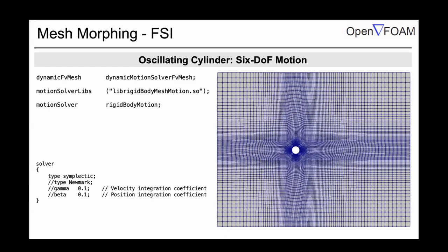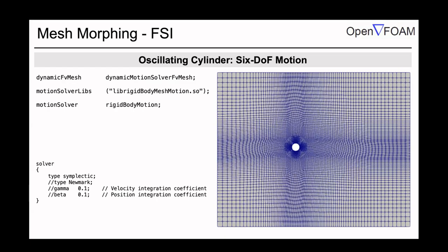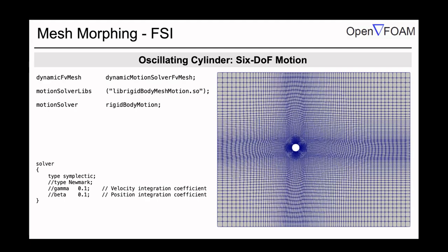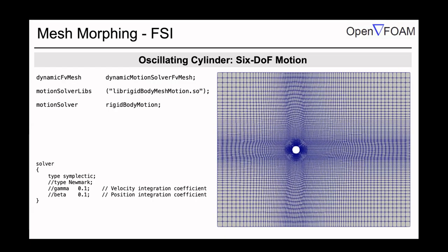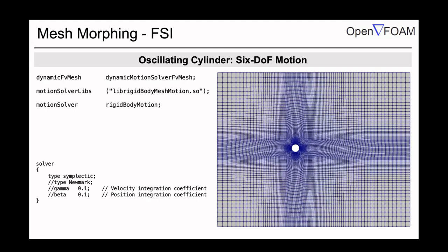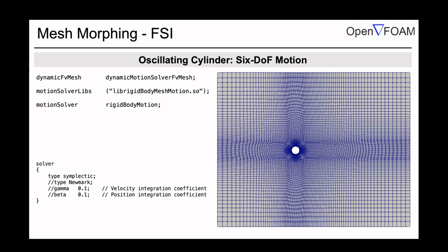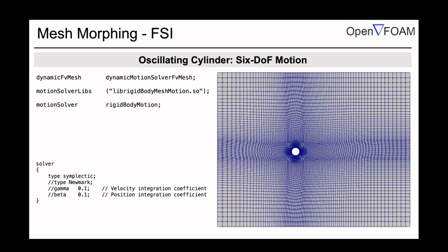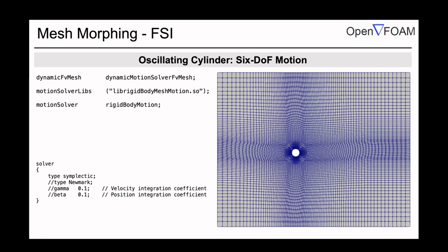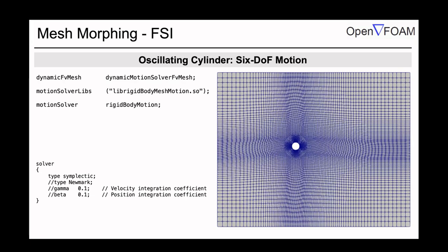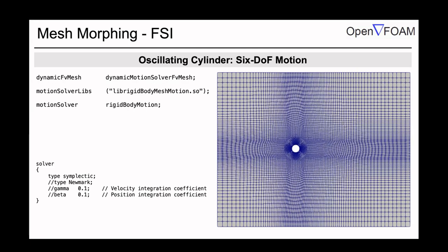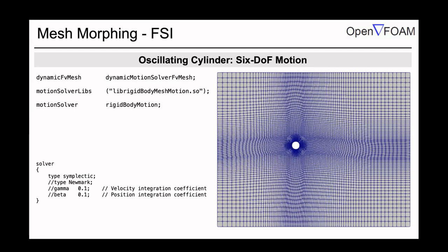And apart from all the structural parameters, you have to use a structural solver, which will do the time integration of the oscillator equation and transfer the displacement value to the Navier-Stokes solver in a staggered manner. The thing that I explained yesterday. So this will be a partitioned weak coupling approach. As I told yesterday, this solver will not work appropriately for a very small mass ratio. Okay, if you want to run this VIV problem for mass ratio 1, you won't get an accurate result.